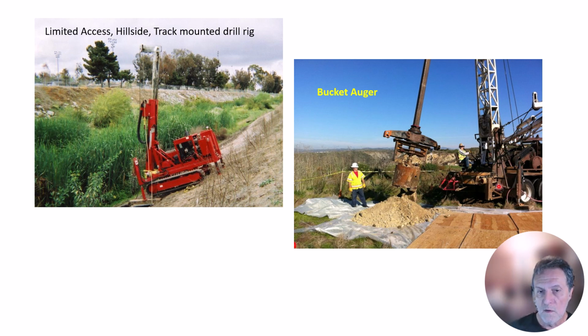Finally, this picture of a bucket auger. Bucket augers have been used in Southern California for decades. I don't know how long. I was using them back in the 1980s. And they're typically used for landslide investigations, where instead of an auger, you have a bucket which drills down, fills up with soil, then the bucket is pulled up and the soil is dumped. That leaves you with a big,